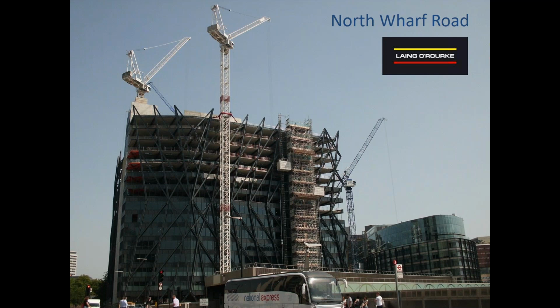On the left-hand side, you can see a crane with only a short stub mast. You can see concrete blocks, like Kentledge, helping reduce the tension loads at the supports of that crane. And it is sitting on a concrete permanent works core. And the crane was only installed in that location when the core had been completed.